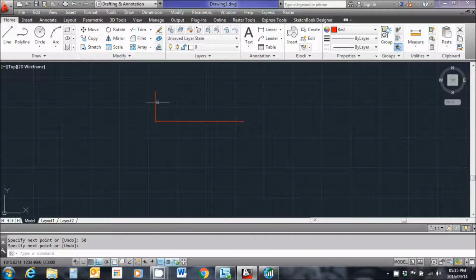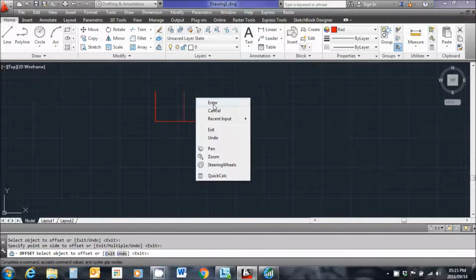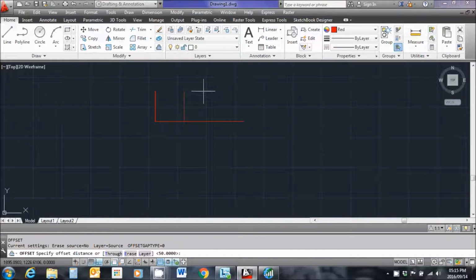Now I'm going to offset this line for the position of the sewer manholes along the horizontal length of the sewer line, and I know that manhole B2 is 50 meters away from manhole B1, so I'm going to offset this line by that distance, which is 50 meters. From there to there. I'm going to repeat the offset for manhole B3, which is 51 meters away from manhole B2. So, sorry, 51 meters, but I didn't say that before.